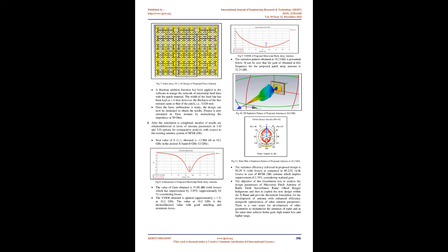The radiating patches must be adequately spaced both horizontally and vertically, otherwise they may lead to interference and result in reduction of overall gain of the array. It was observed that a horizontal spacing of 7.18 mm between two patches and a vertical spacing of 6.36 mm results in the best overall efficiency as far as basic antenna parameters are concerned.